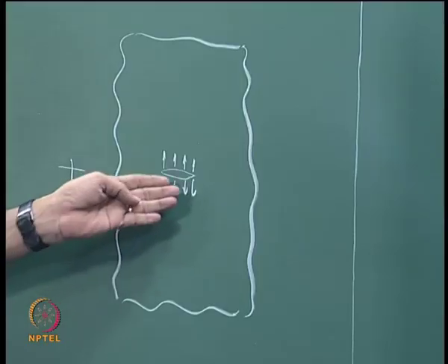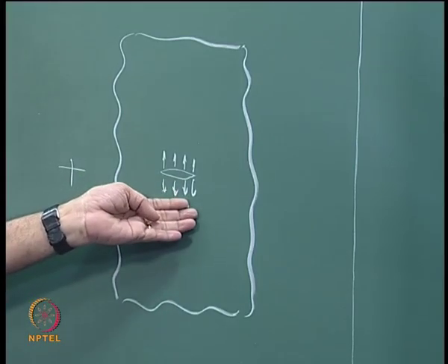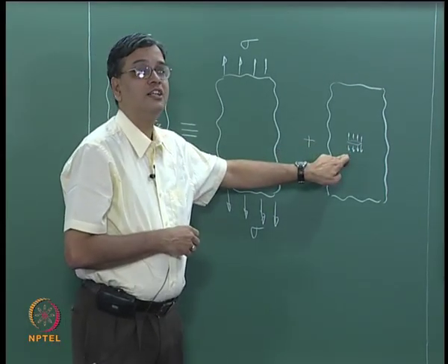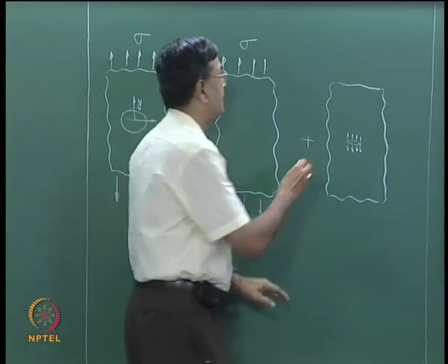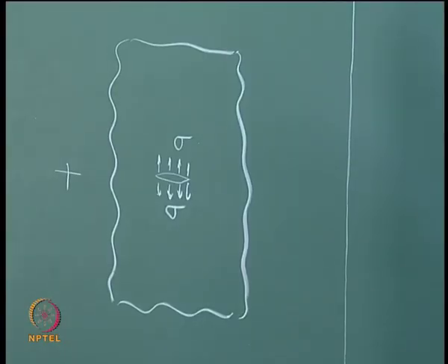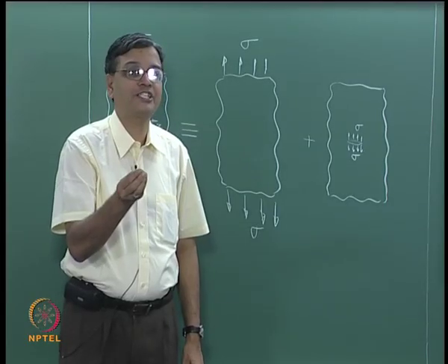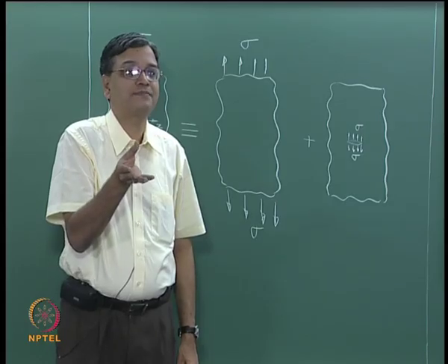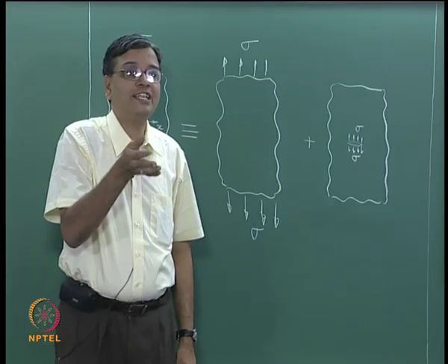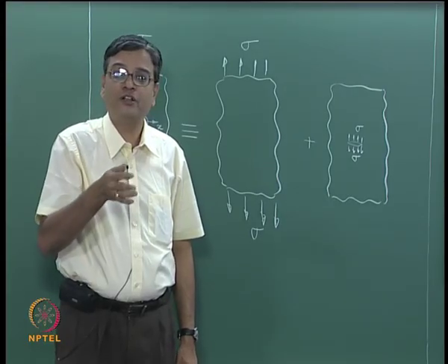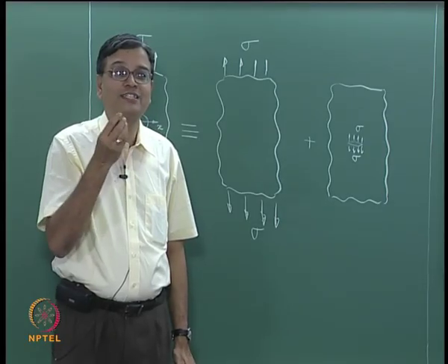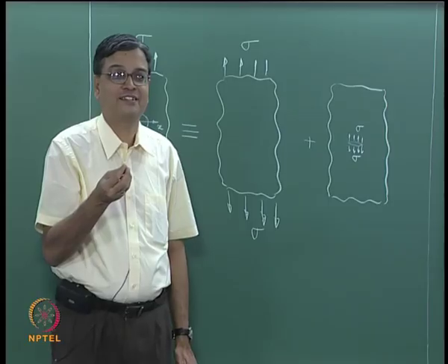And from such consideration that stress intensity factor is same for this problem and the final problem, this force or the load is nothing but sigma. It is like you supply an internal pressure and then the crack opens up. So, from the energy release point of view, whatever the work done I do to open it is the energy that is required for me to form the two new surfaces. See, mind you, this is a thought experiment, you will have to visualize this mentally.